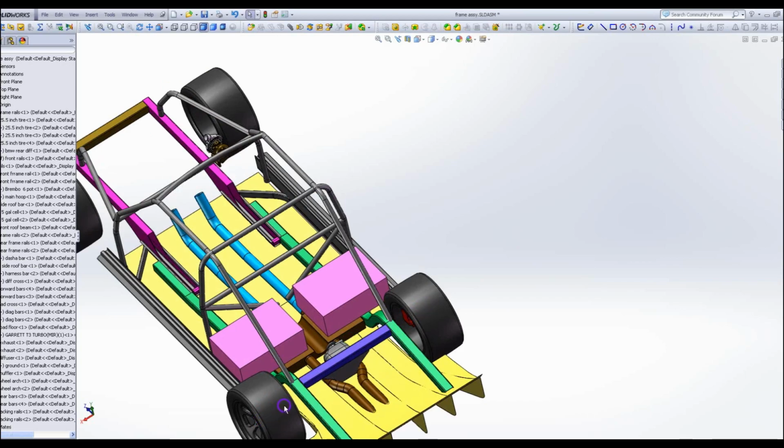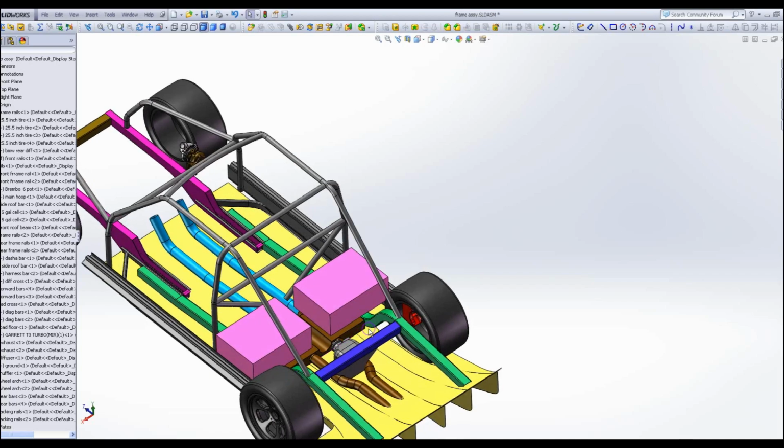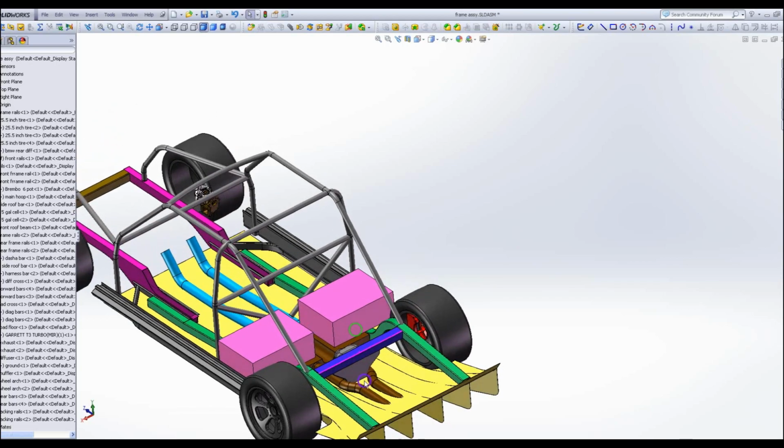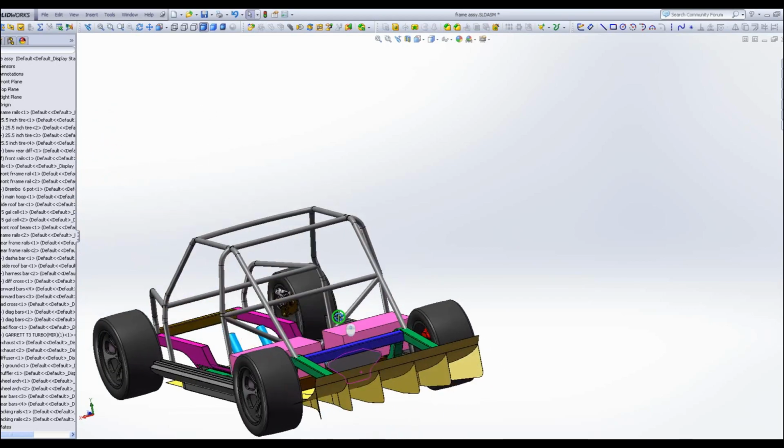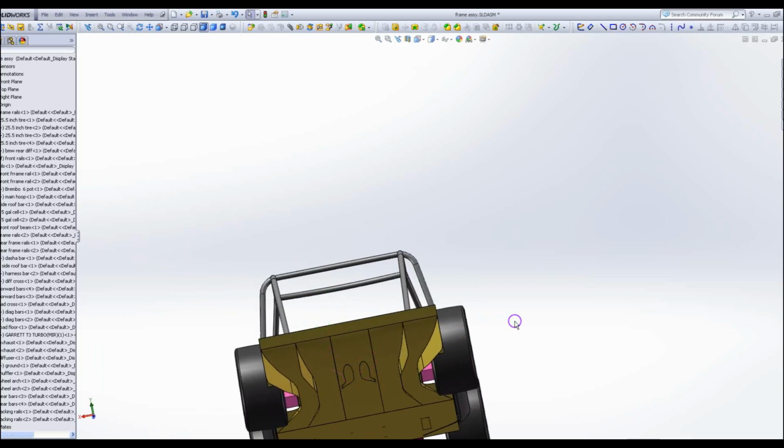I do have some plunge that I can steal, especially since I'm moving this differential forward and up. So those axles will be on a little bit more of an angle than they are in the factory scenario. So doing that for a couple of reasons. Polar moment of inertia for one, and then when this thing squats, I want the angles to be even. So in normal ride height, the axles will be kind of coming uphill a little bit. And I also want to keep this differential out of the diffuser. So I needed to push it up a little bit.